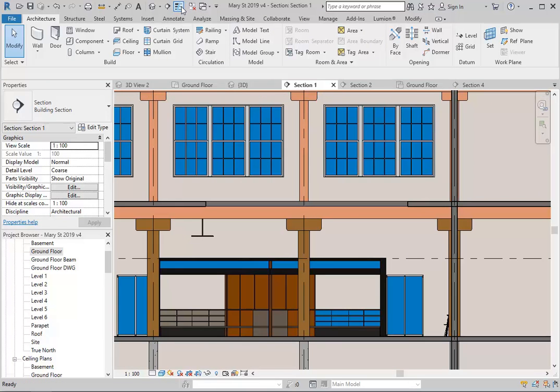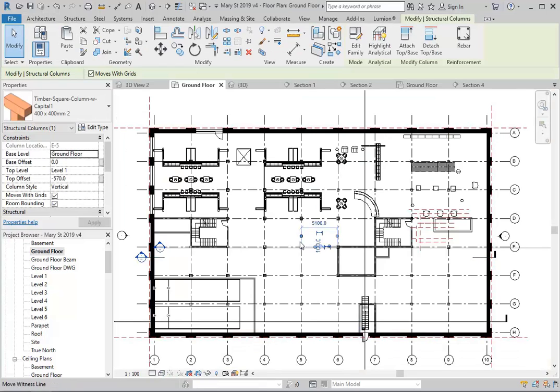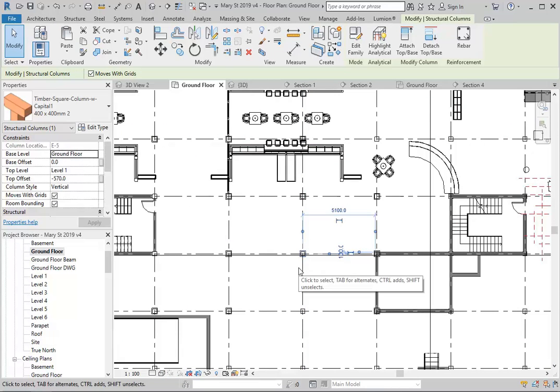You want the line weights here. And then you should be able to see it. So then I can see that I've got a column sitting in the middle of that shaft. And do we want that? No. So we've got to delete the columns. So maybe to finish off, very last thing I'll show you for this. We'll come back and do the joists later.